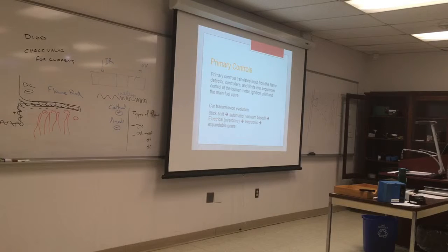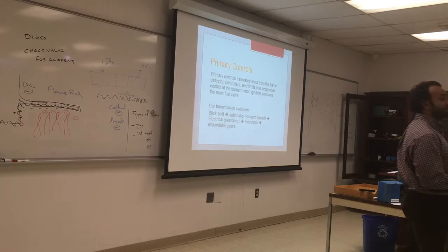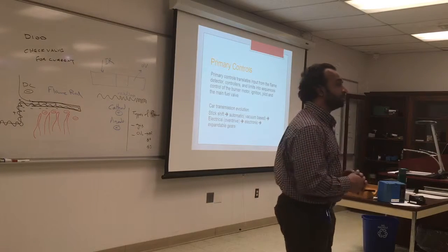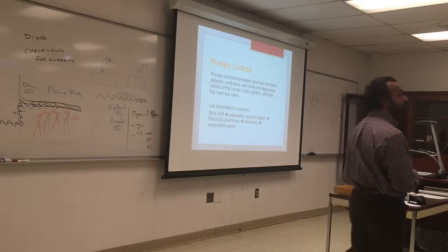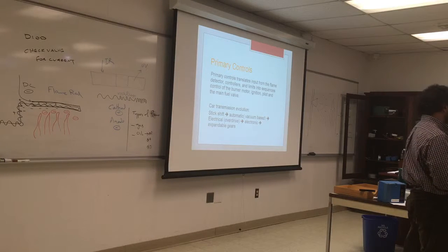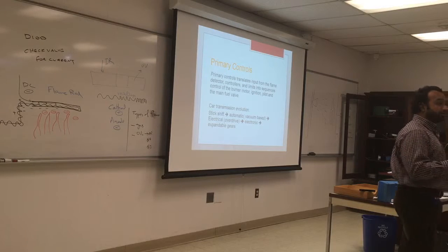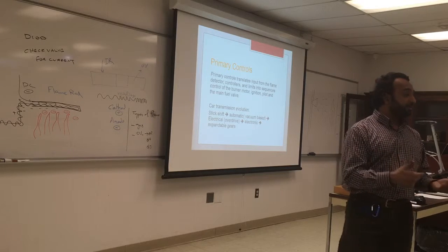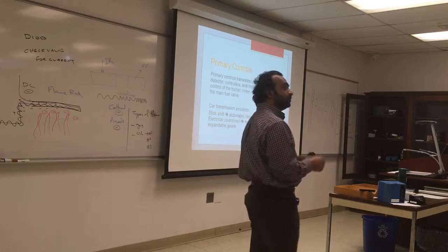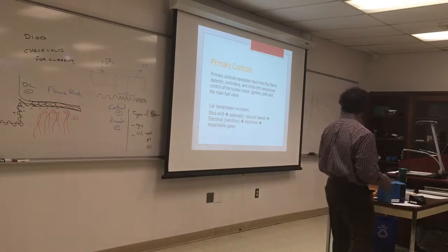It's like when you have a check engine light in your car, and you go and plug in your computer, and the check engine light gives you a code. You run the code, and for example, it tells you oxygen sensor. You change the oxygen sensor, and you see that the error did not stop. So you change all the possible codes. Now they are getting better and better, where you can actually get a specific code that tells you what happened, with date and time and how many times it happened.